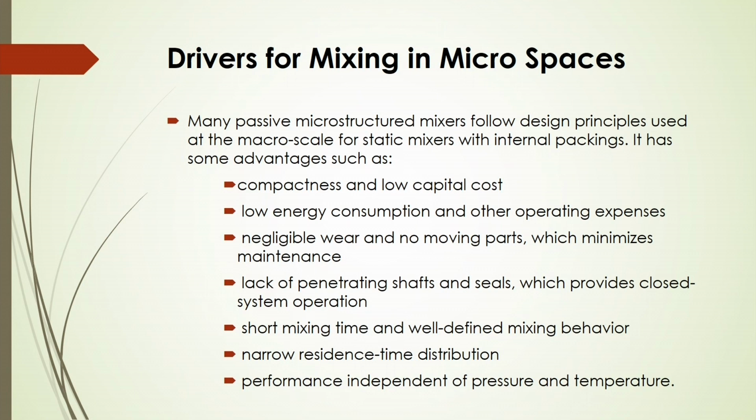Now, what should be the drivers for mixing in micro spaces? We are talking about microchannel based reactors. Of course, in very small volumes or micro spaces, there are many passive microstructure mixers that follow the design principles used in micro scale static mixers with internal packings. It has some advantages: compactness, low capital cost, low energy consumption and other operating expenses, and lack of penetrating shafts and seals.